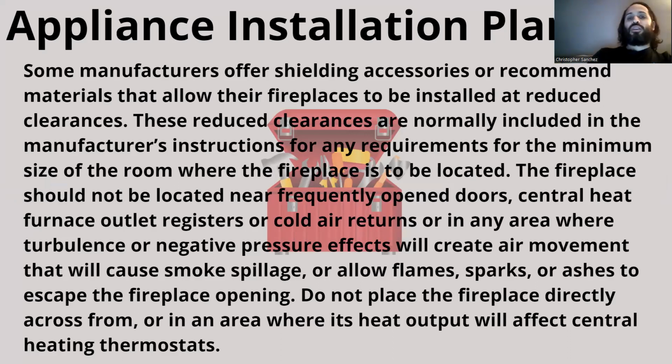The fireplace should not be located near frequently open doors, central heat furnace outlet registers, or cold air returns, or in any area where turbulence or negative pressure effects will create an air movement that will cause smoke spillage or allow flames, sparks, or ashes to escape the fireplace opening. Do not place the fireplace directly across from or in an area where the heat output will affect central heating thermostats. Pretty self-explanatory there. Again, this is in regards to the location, to airflow, to where we see thermostats, things like that. That's really, really important that we're looking at.